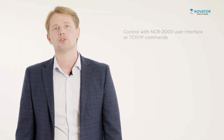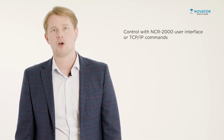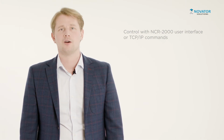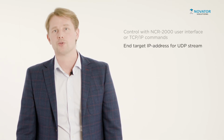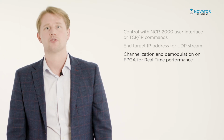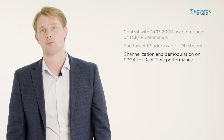Before this video ends, I'd like to highlight some features. You can control the NCR 2000 either with a shipped user interface or with TCP/IP commands and let the server run as a service in Windows. By selecting the IP address for each channel, you can stream the data over UDP to a selected target on your network. Selecting a channel of interest with channelization and demodulating the data, you reduce the traffic over network heavily compared with streaming the full bandwidth.